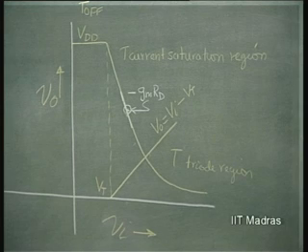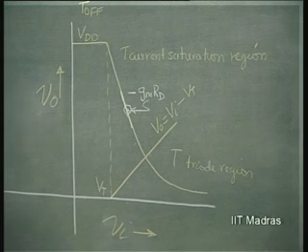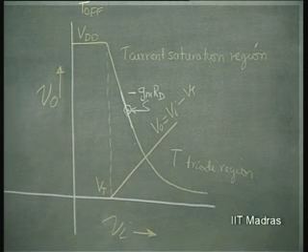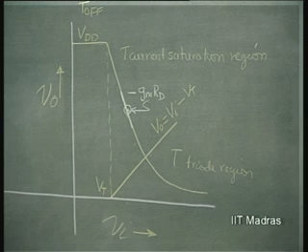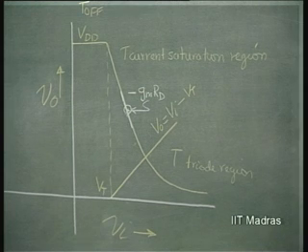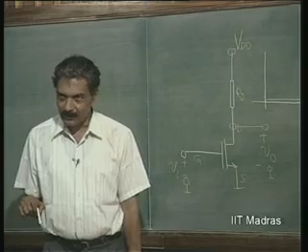That is the small signal gain of the amplifier. This is the common source amplifier, and this Gm keeps changing as you go further and further. As the current is lower, the Gm is going to be lower, because Gm is really 2k into Vgs minus Vt, and current is k into Vgs minus Vt whole squared. So, as current is lower, Gm is going to be lower.